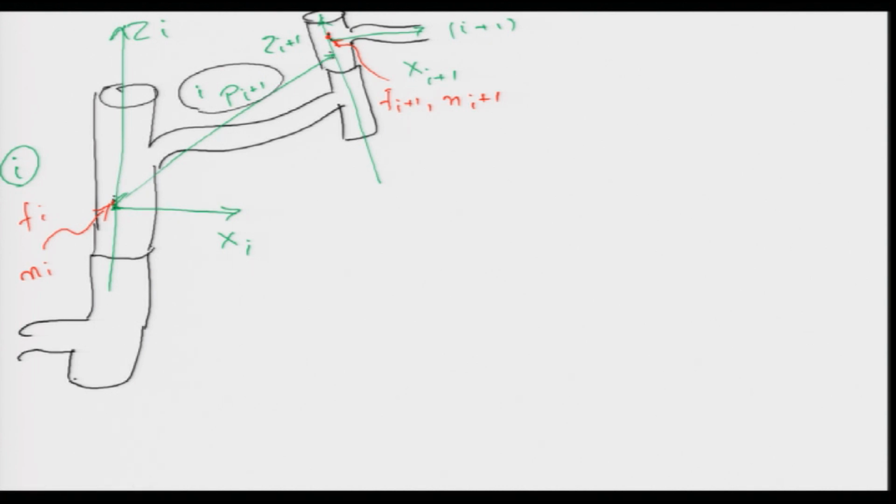Okay. So, the moments are going to get transmitted and the force will also get transmitted, but this force here will also cause a moment about this axis now. Why? Because there is a force F i here. So, the force into the distance will cause a moment here now. So, forces and moments are going to move, and a moment will be created also, because the force is acting here and this force into the distance will be a moment about this point.